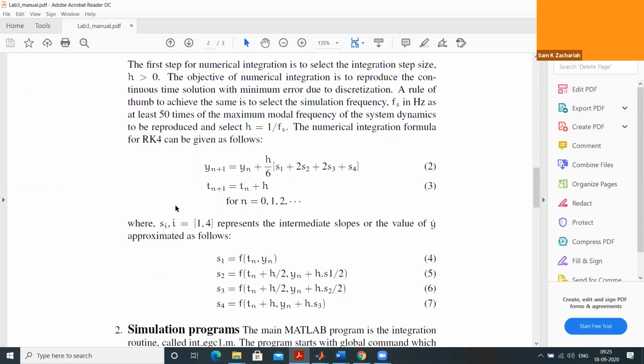So minus 3 dB is one specification. With respect to amplitude, the amplitude of deflection will be 1 by root 2 times the amplitude of the command. And if you specify the bandwidth as a minus 90 degree bandwidth, what it means is that the phase of the deflection will be lagging behind the command phase by 90 degrees. So these are the two typical bandwidth specifications. But now in our lab, we are only using the minus 3 dB bandwidth. Any doubts so far?